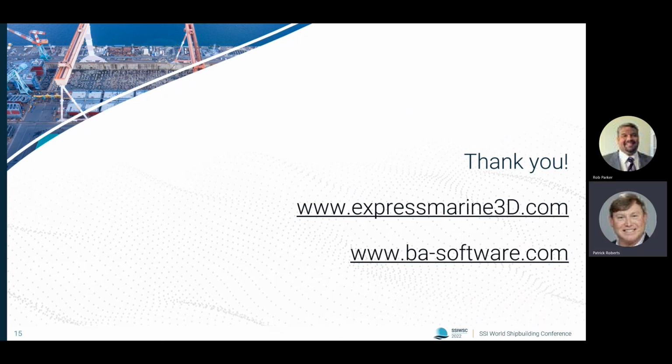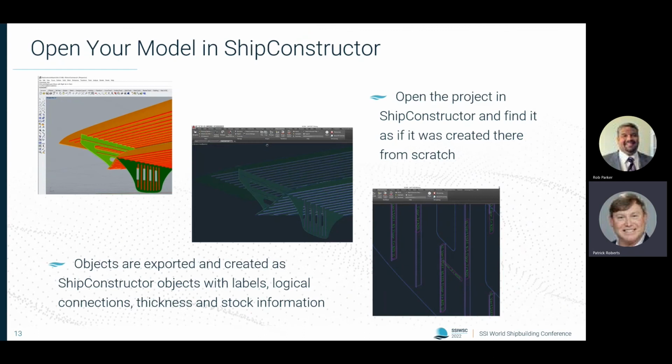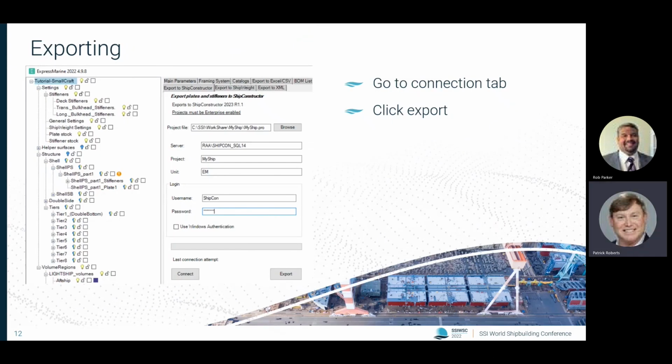Yes. So it certainly creates the planar groups, and I don't know if it's easy to see here, but there is. When you connect, this is for export, then you give a name of the unit. So whatever you export will go into this particular unit of your ShipConstructor project. And yes, planar groups will be created. I can mention as well that the tree view you see here, that's your vessel, and you can select also parts of it to export. It's not necessarily all or nothing. You can say, I want to do this deck, these bulkheads into this unit.